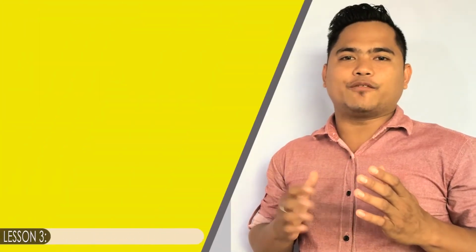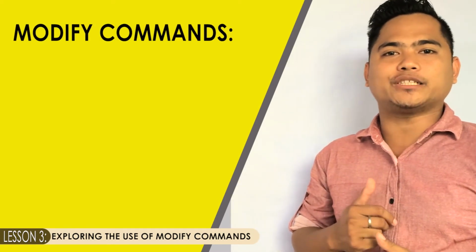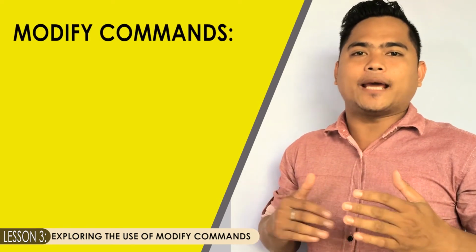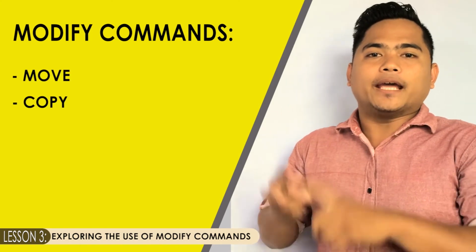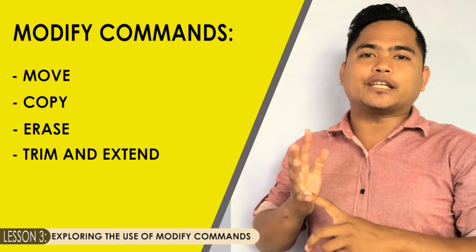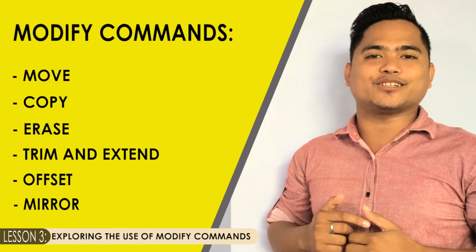Part of this lesson 3 of the tutorials shows how modify commands can be used in accomplishing your CAD projects. These commands are used in modifying or editing drawings. Move, copy, erase, trim and extend, stretch, offset, and mirror commands were some of the commands presented in this section.